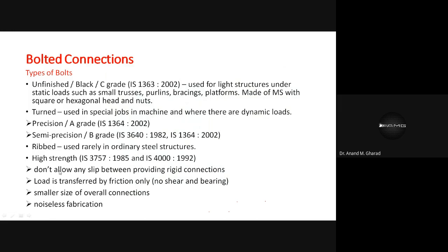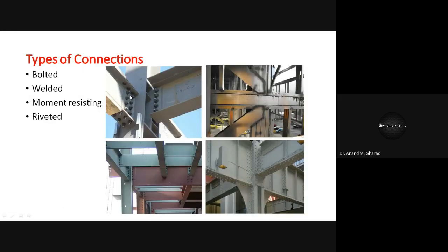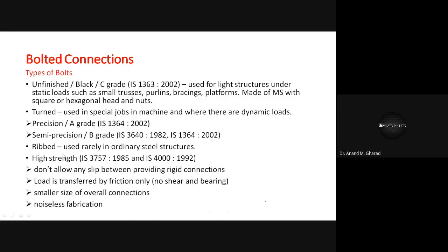And then there is the ultimate load which that high strength bolt may carry. Depending on those values, the overall design will get revamped, and based on that revamp you will see the number of bolts reduce. But even though the number of bolts is reduced, the strength will not vary. So that is the beauty of high strength bolts.